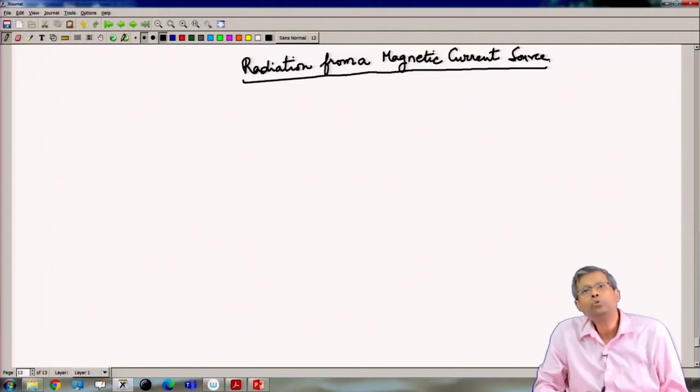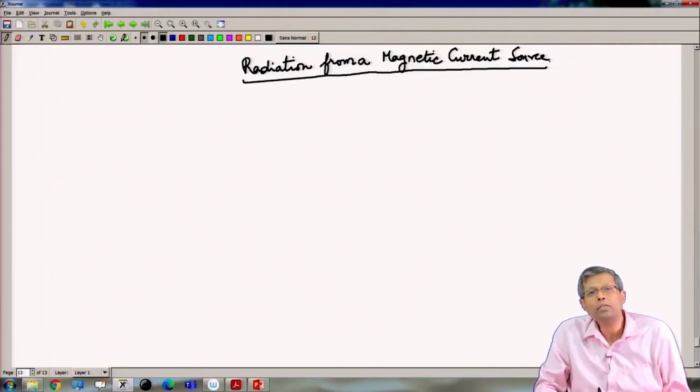The magnetic current source in electromagnetics actually is as important as the electric current source. We will soon see how the magnetic current source accomplishes its task and how it simplifies, or I should say enables the field computation. Without the magnetic current source, we cannot solve an electromagnetic slot coupled field problem.